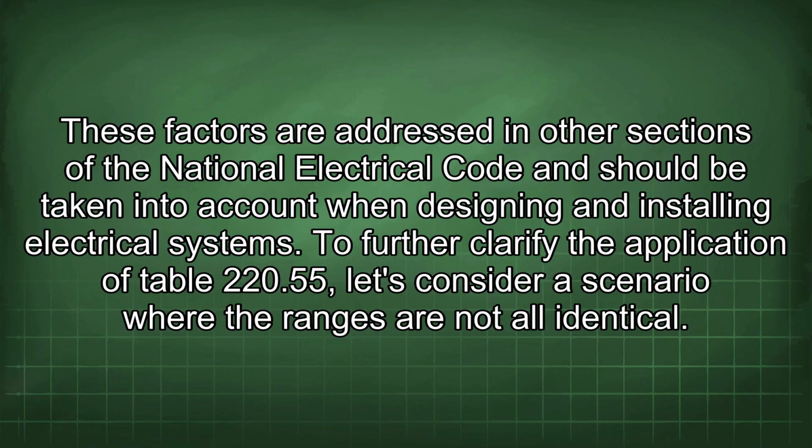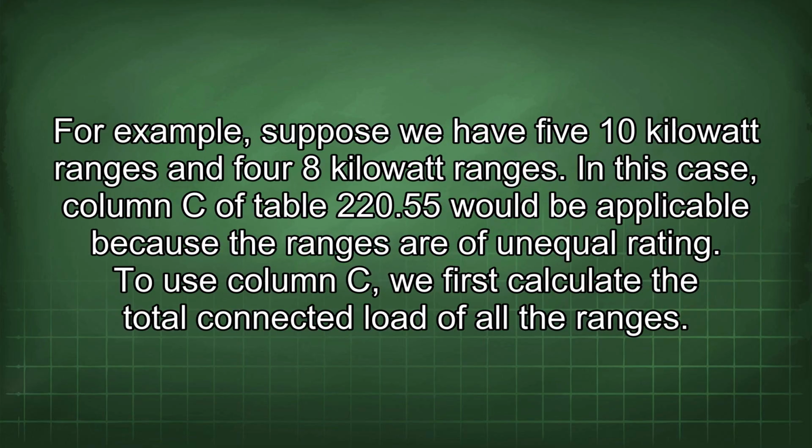To further clarify the application of Table 220.55, let's consider a scenario where the ranges are not all identical. For example, suppose we have 5 10-kilowatt ranges and 4 8-kilowatt ranges. In this case, column C of Table 220.55 would be applicable because the ranges are of unequal rating.